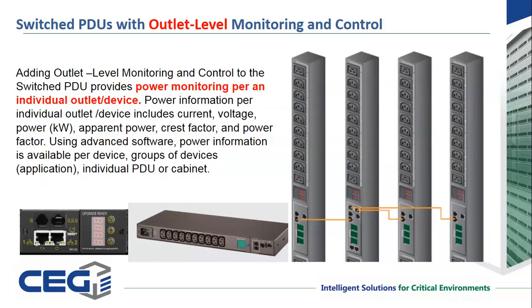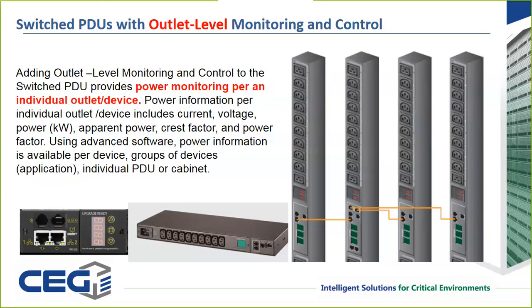The other use is perhaps in co-location, where you may have several different clients or departments within the same company plugged into the same cabinet, and then you can branch out and associate just particular gear to a particular client, and give that customer the control over just his particular gear. So this is the most granular means of doing power strip monitoring and control at the outlet level.